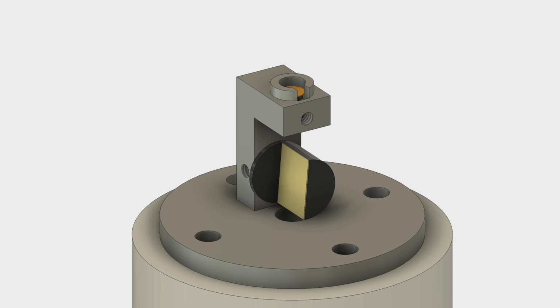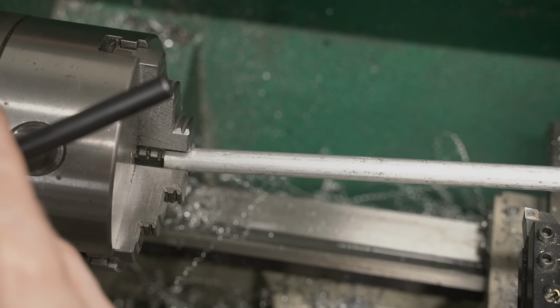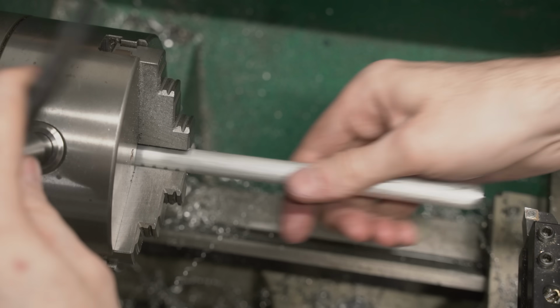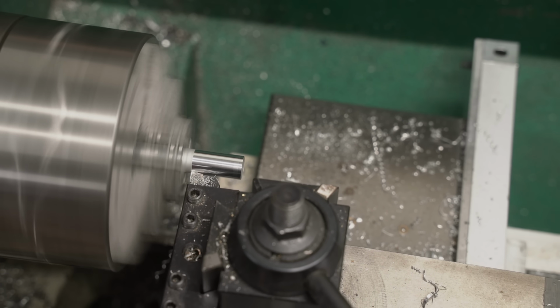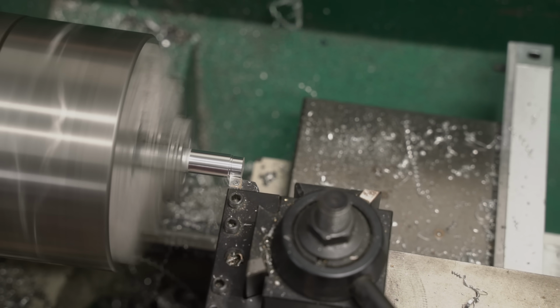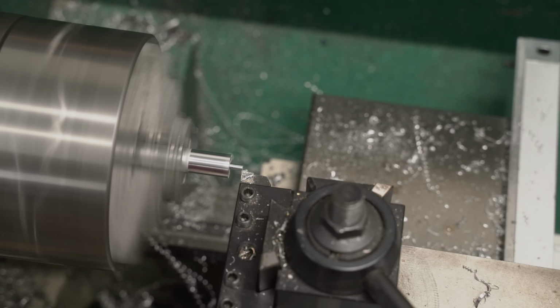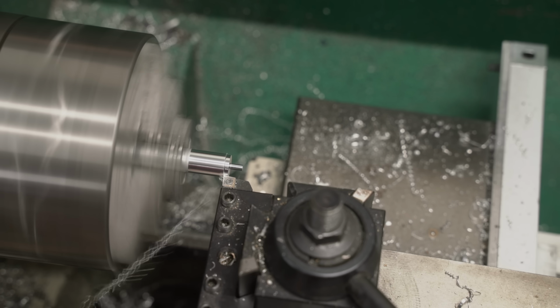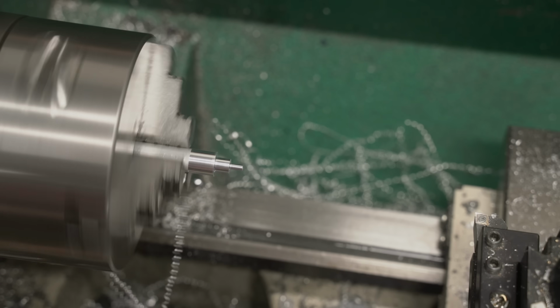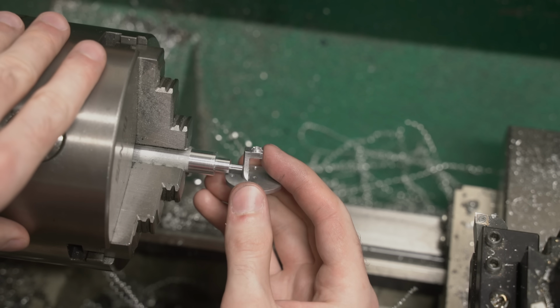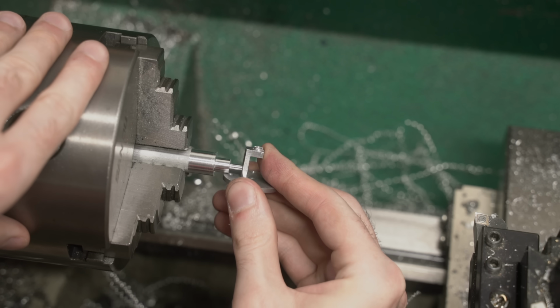Okay, time to make the movable mirror. This part is pretty simple, but the order of operations really matters for small parts like this. We start with an aluminum rod and then clean up the diameter. Then we machine the tiny 3mm shaft first. After that, we machine the mirror's outside diameter. Once that's finished, I can test to see if the shaft will fit in the sample holder.